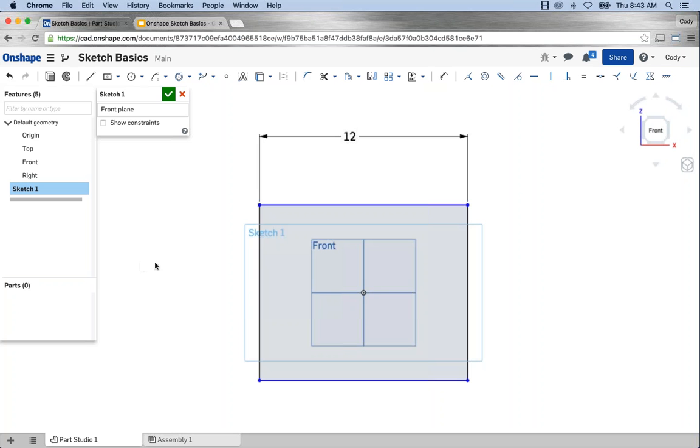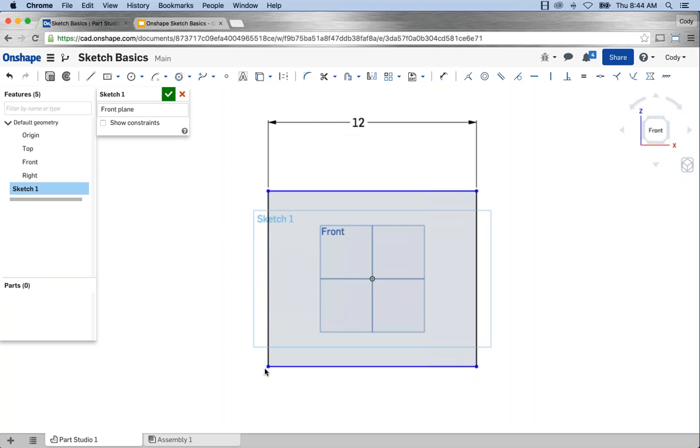And so you get that visual cue that these lines, the width of them is defined, but the height is not defined, right? That's something that I'm missing here. These points are not, right? The height of this rectangle is not defined. So just some things to keep in mind. You do need some level of dimensions to your features, and you really want everything fully defined, right?